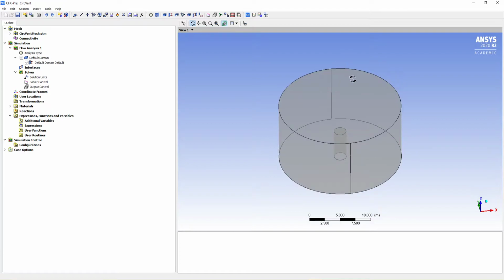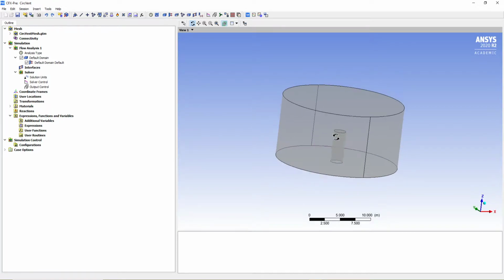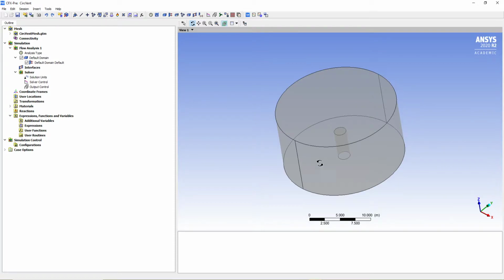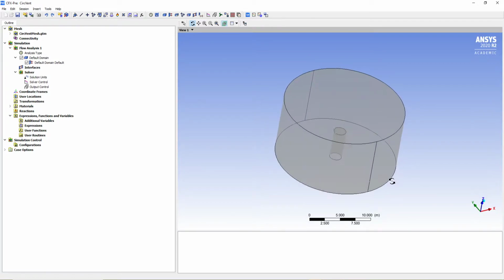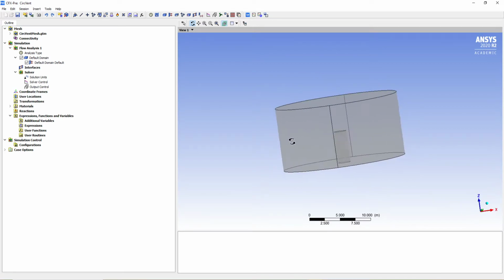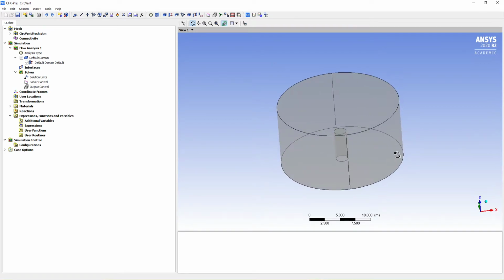We have two walls. So basically, one wall is gonna be used as the inlet for the wind to come in, and the second one is going to be the opening. Why are we choosing opening? Because this time around, we don't know if the wind is only going out of the wall, because we're dealing with the free air. It's much harder to predict where the flow of the fluid is gonna go to. So this time around, we're gonna use an opening boundary condition, okay?